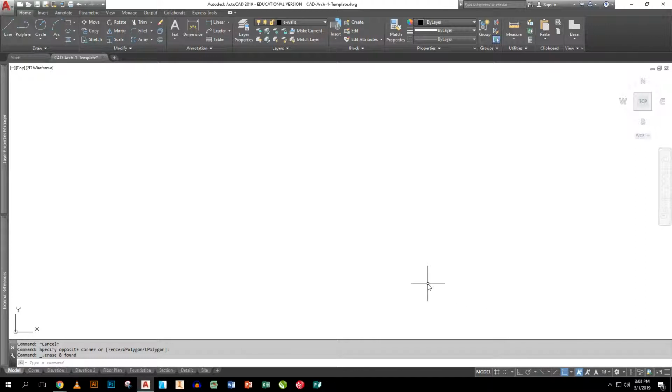So as I'm doing that, that's great. Now, one thing you do need to be aware of, and this program does do three-dimensional. Don't mess with it as a beginner. You have to keep track of your world orientation according to your UCS. Now, your UCS is marked right here. That's your user coordinate system. It can change depending on what you want.